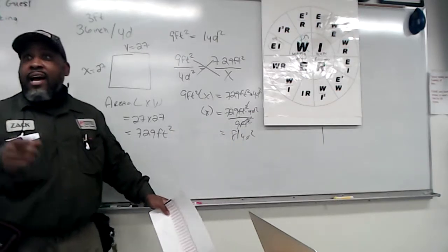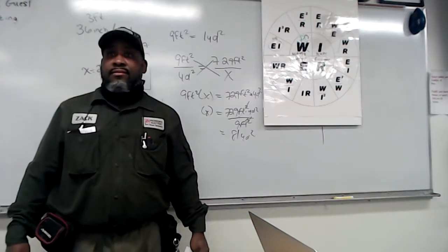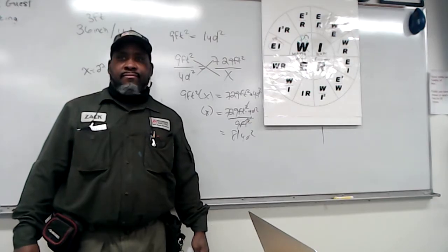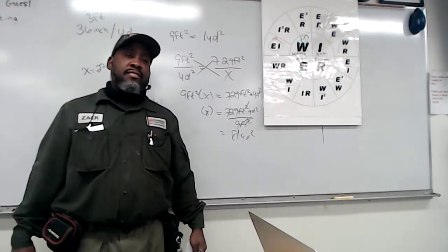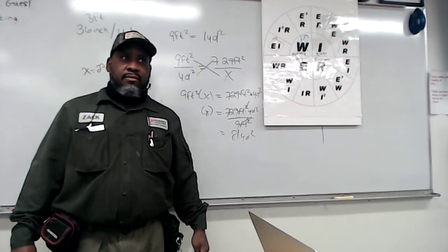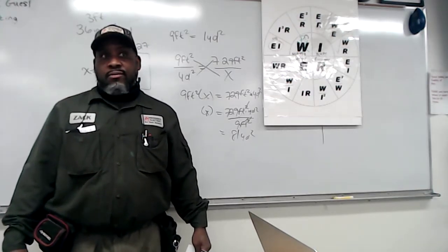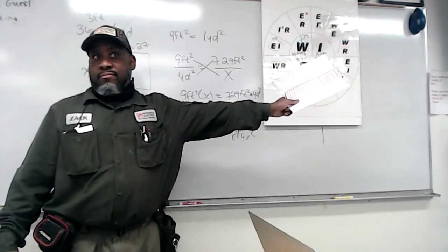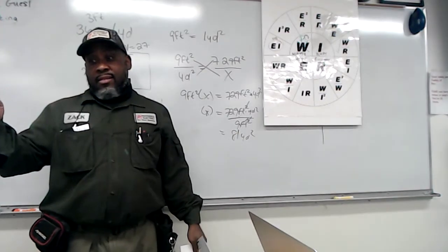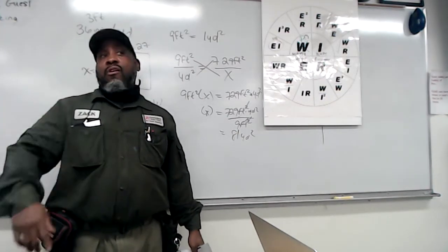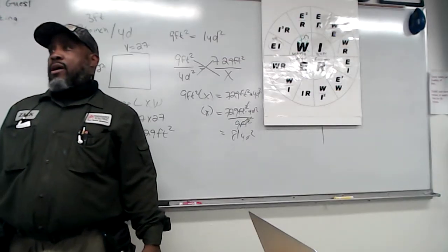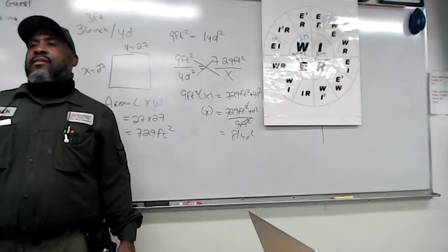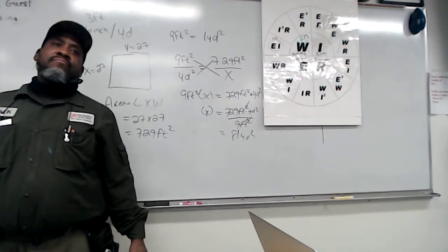A house. Is this a house? So the code doesn't require a plug to be there because it's commercial. That's why it's 0. Remember that. It's not a house. What does the question say it is? It's an office. So it's not required to have a plug. If it was a house and it's less than 2 feet, it still would require one, based on code. So 0 either way. Even if you thought it was a house, you still should have got 0.